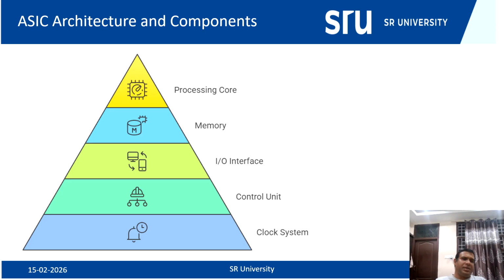Now, ASICs can be classified into different types based on their design approach, which is known as full custom ASIC. The full custom ASIC is completely designed from the transistor level, or we can say designed from scratch. This is called full custom ASIC, which offers the maximum performance, lowest power consumption, and smallest chip size, but it requires high development time and cost.